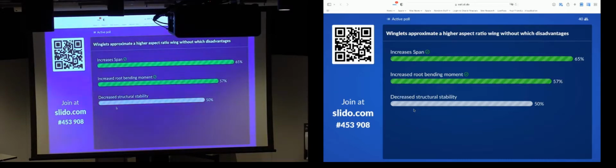If we make their wingspans just a little bit larger, they go in code D. All of those stands that they park next to each other, and there's not a lot of space, they now can't fit them in. A330, A350, 787, the original 747, they were code E. We make their wings a bit longer, they become code F, like an A380. Far fewer stands.